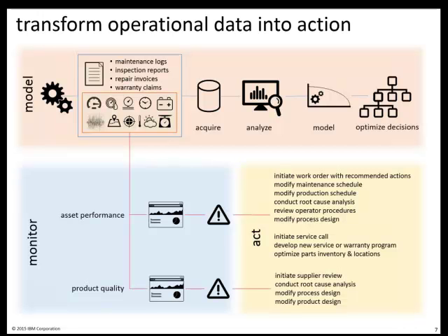We can complement that with historical information, operational data from those assets, and that's represented by the various icons. There's time, temperature, weather, humidity, vibration, etc. And via a combination of both the unstructured and structured information regarding that asset performance, we can do an analysis of what particular data factors, what data sets, what information really helps to describe the performance of that particular asset. And then from that, build a specific model that describes, essentially, if you will, a PF curve for that asset that predicts potential degradation very early on, so you have a much better understanding and ability to proactively address potential asset failure or degradation.